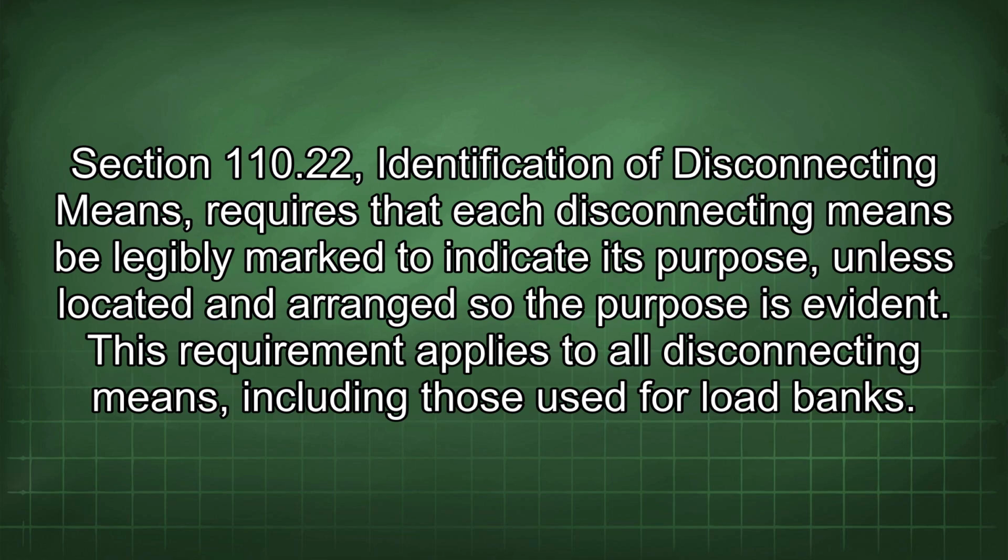Section 110.22, Identification of disconnecting means, requires that each disconnecting means be legibly marked to indicate its purpose, unless located and arranged so the purpose is evident. This requirement applies to all disconnecting means, including those used for load banks.